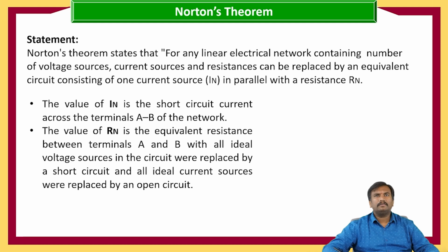First, let us go with the statement of Norton's theorem. Norton's theorem states that any linear bilateral circuit which consists of voltage sources, current sources, and resistances can be replaced with a single current source in parallel with the resistance, where the value of resistance is the equivalent resistance between the load terminals by replacing the sources to 0, whereas voltage source is replaced with short circuit and current source is replaced with open circuit.